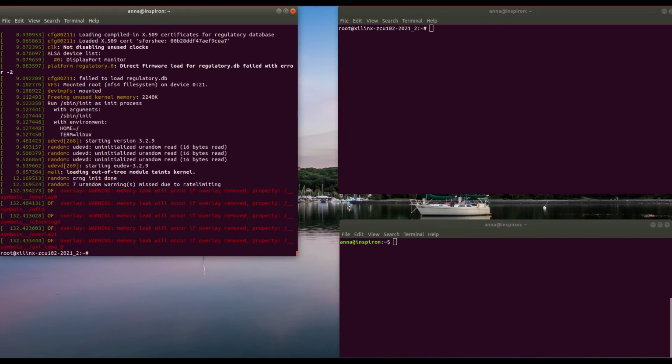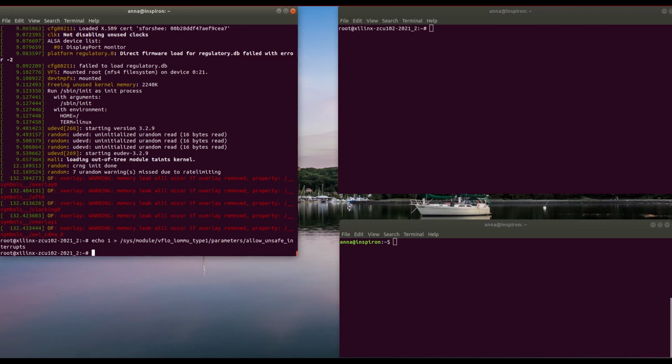After this, some kernel messages, which are basically innocent, pop up, and we can understand that the overlays are now part of the device tree. Next thing for us is to bring the VFIO platform driver into the picture. To do this, first we have to set up some parameters in order to enable the VFIO IOMMU support. Then we can install the driver in the system.